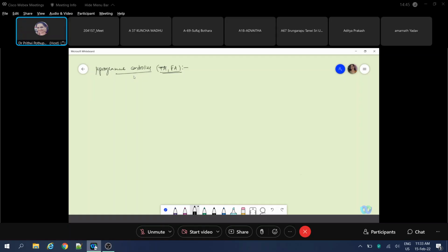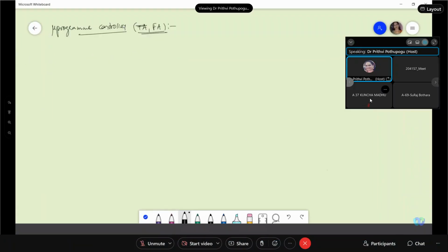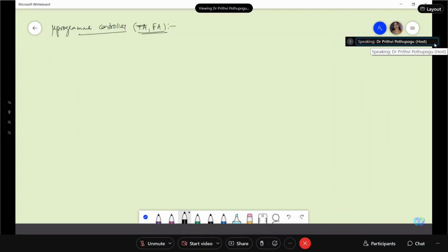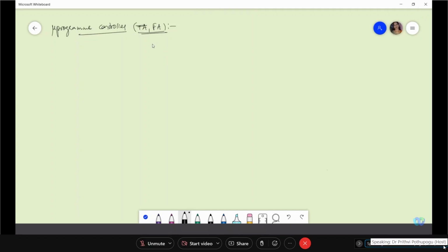The assumption made by Wilkes is that no conditional output should be there. Why? Because if the conditional outputs are there, we need to have an output bit to decide whether it should be coming conditionally or unconditionally. So a few of the outputs can be conditional and unconditional in the ASM.